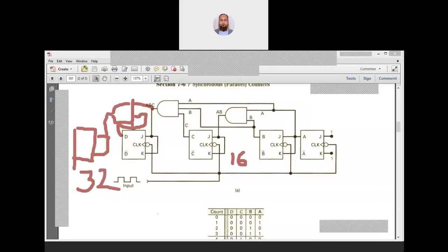So you can see that the next flip flop inputs are the previous flip flop outputs with the AND gate. So this process is continued. After the first flip flop, where the inputs are 1 1, in the second flip flop the previous output is the input, and in the third flip flop the input is not given directly, but it is the AND operation of the previous two outputs.